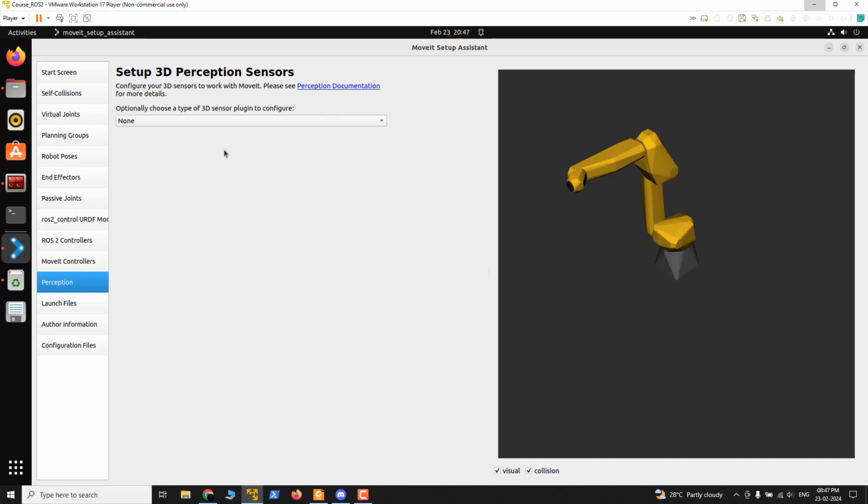So it will be converting this point cloud into Octomap, which is helpful for obstacle detection. So for example, if there is any dynamic obstacle passing nearby the robot, the depth camera can convert the point cloud into Octomap, which can be avoided by the robot. The Octomap is basically obstacle. So when we do the planning, the robot will be avoiding that.